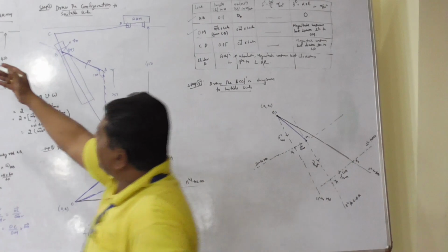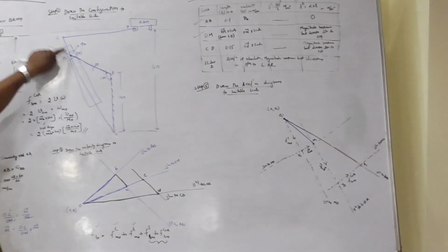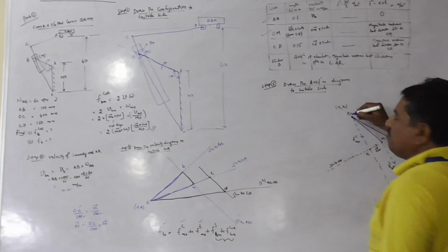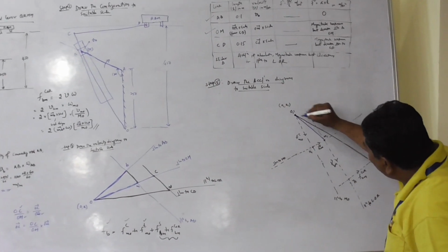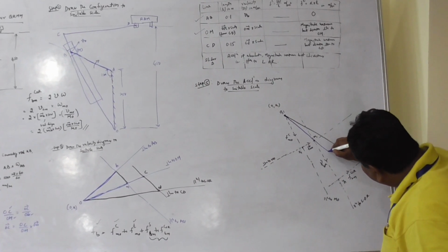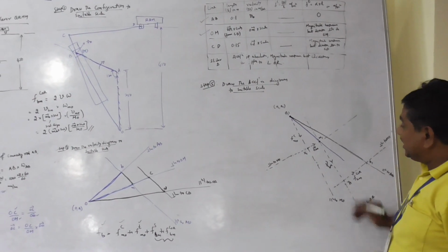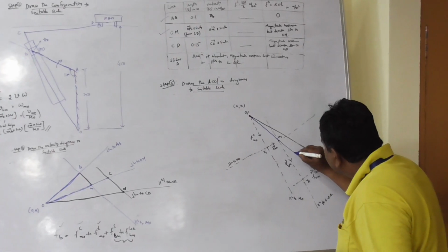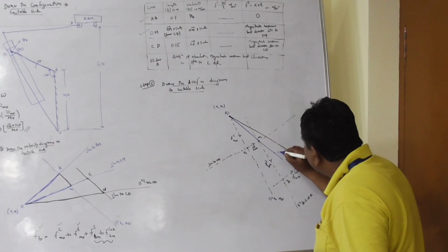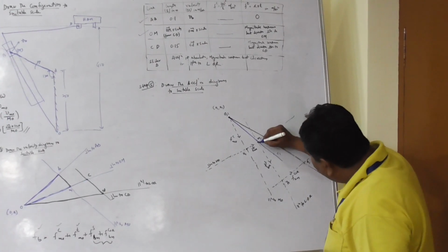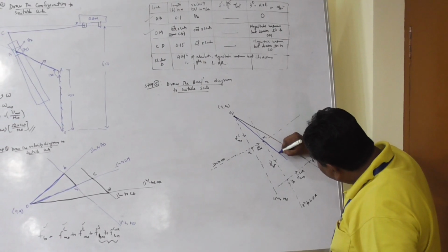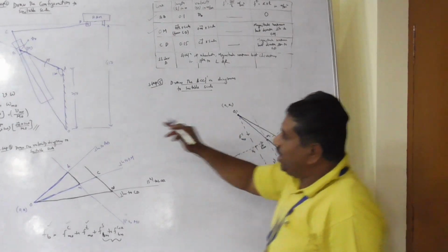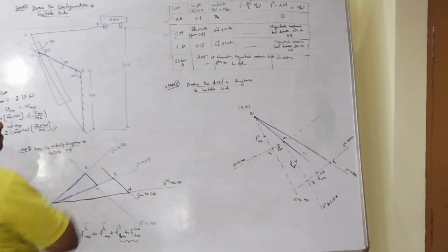Where is the point C? C is on the extension of OM. Therefore, in the acceleration diagram also, O1 M1 is extended in the same proportionate as in the actual configuration. Fix the point C1. Now I have the oscillating lever OC, as O1 C1 is the acceleration image of link OC.